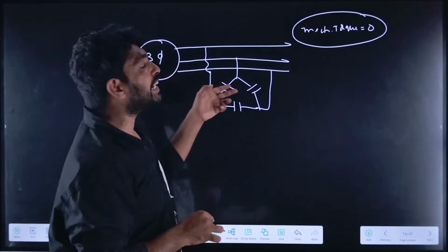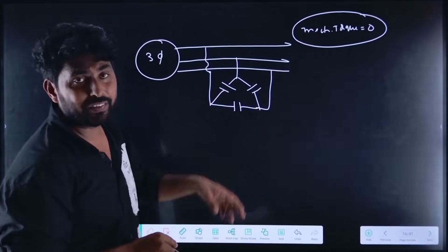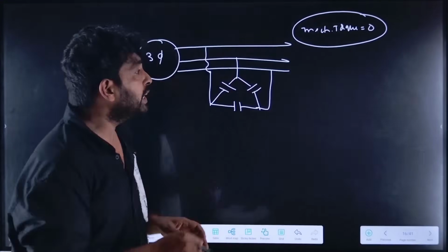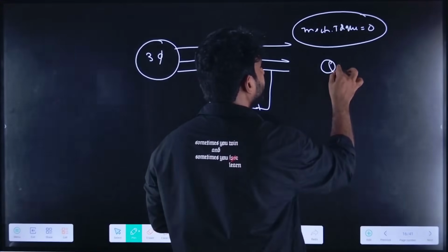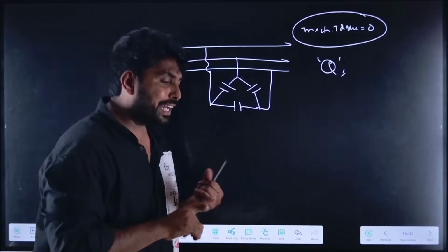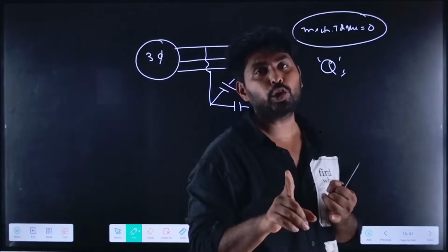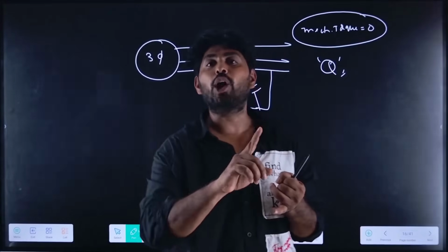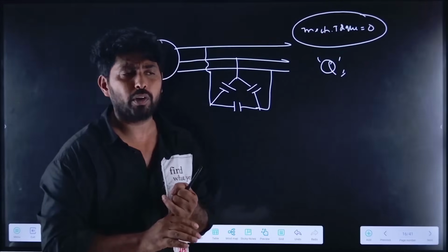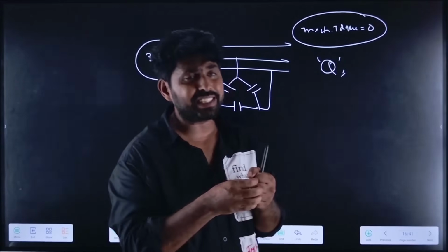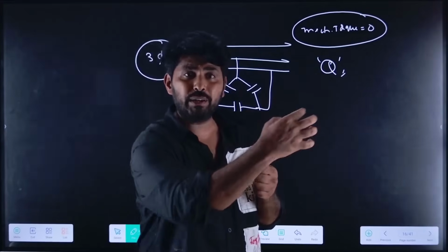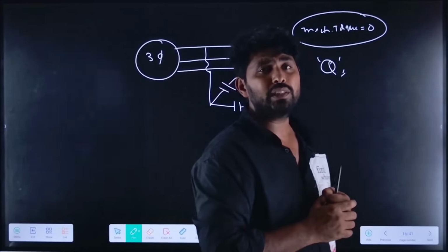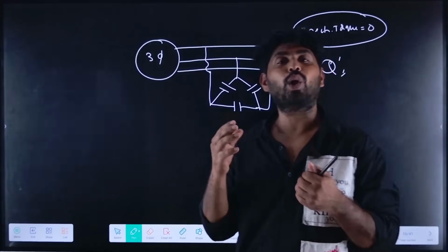There is only reactive power required to supply the capacitive load, so here there is a component of Q. When you are explaining the three-phase reactive power to somebody, don't tell them that it is an oscillating power. In a three-phase condition, it is not an oscillating power. It is constant, and in a physical meaning, it is not at all defined.